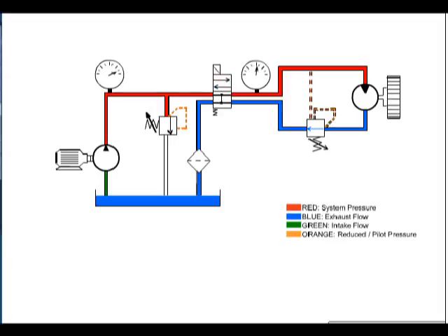When we de-energize the directional valve, remote pilot pressure is lost, allowing the valve to close. The inertia of the load will now drive the valve open via the internal pilot, giving us dynamic braking. Now that you understand the application of a brake valve, push Energize, then Stop to see the valve function.